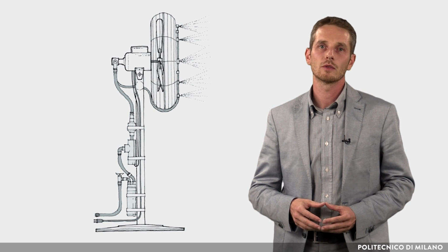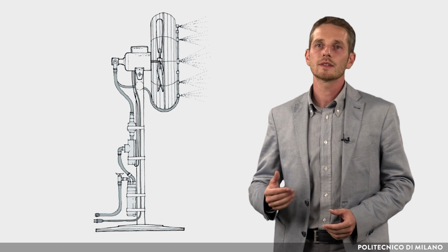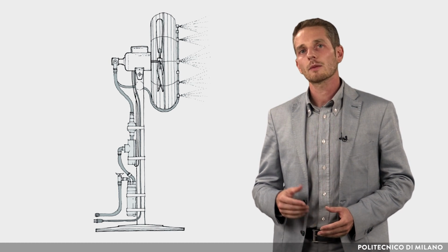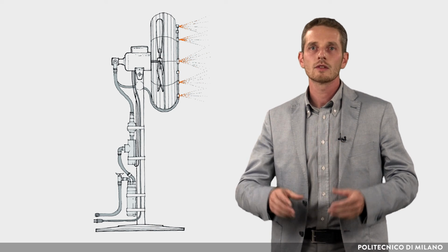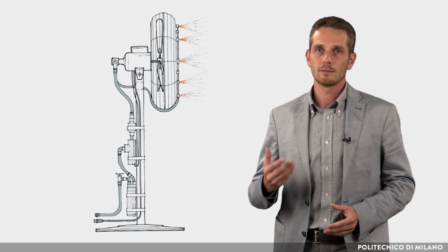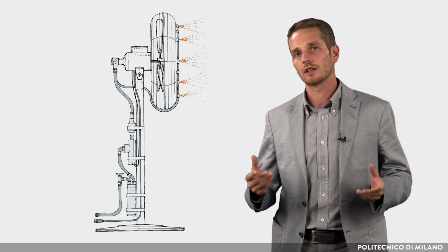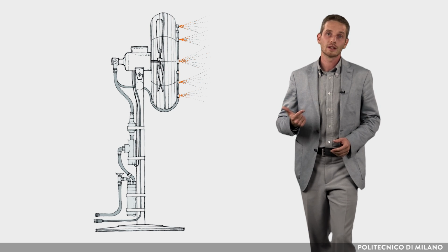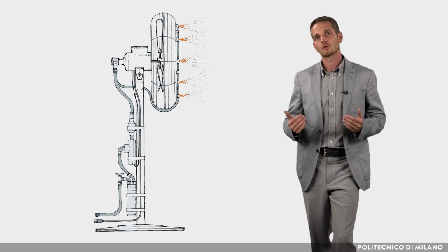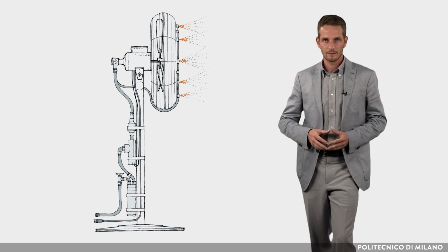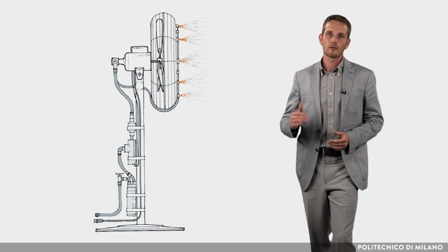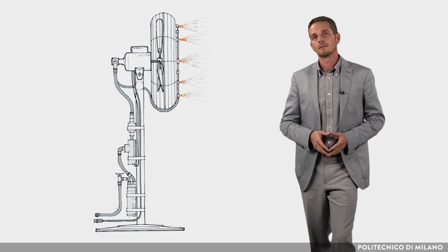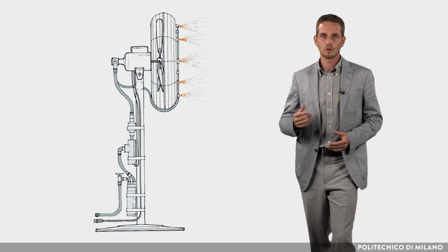In hot arid climates, the effect of a fan can be improved by exploiting the evaporative cooling effect with the use of a misting fan. It is a normal fan equipped with fog nozzles, which is designed to produce a very fine mist so that the water evaporates quickly. It combines evaporative cooling and convective cooling, at the same time reducing the temperature and increasing the velocity of the air. The improvement in the level of comfort can be significant. Misting fans are also appropriate outdoors.